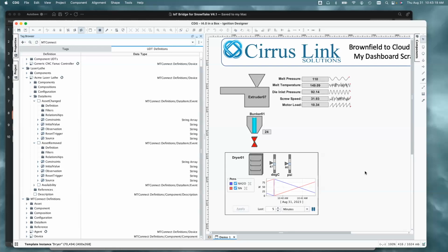Well, Jan, I never try to get into an OPC versus MQTT discussion. I think they both have their strengths and benefits. OPC, as far as on-prem polling, you've got to open ports, find those OPC UA registers, and get them configured. And it's so complex.